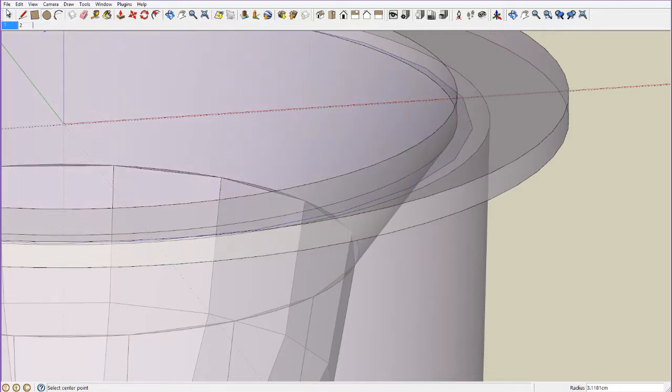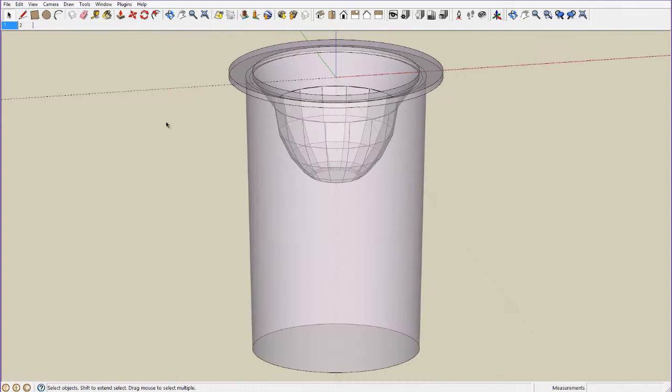Now we have created a circular disc here, and we don't need the surface component or the fill component of this, so we just simply select the surface and delete it, but you'll note that the outer ring is still there. It's perfectly in line with what will be our insert point, and that's all we need to do to have this prepared for the cut opening option. Alright, so now jumping back here, we now have all the geometric elements for creating our light fitting.